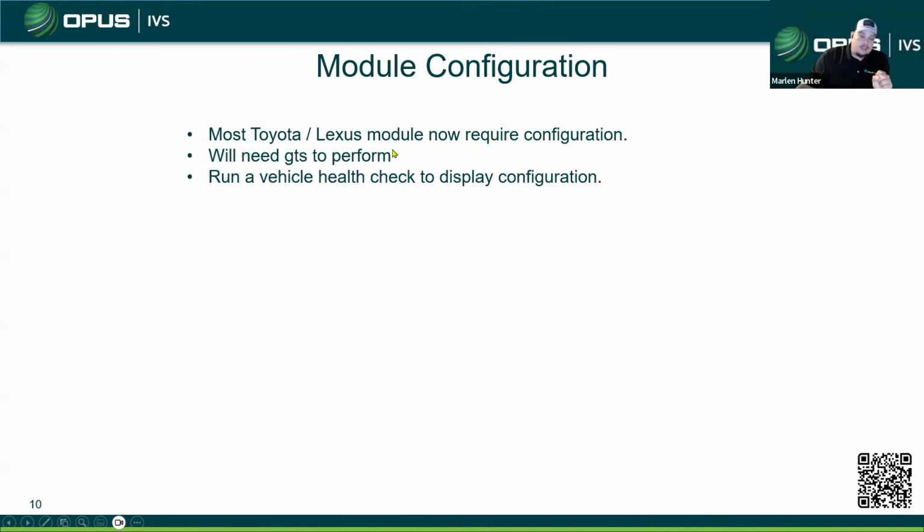Module configuration. There's actually a good service bulletin. I should have put it on here. Depending on the vehicle you have, that will show you a complete list of all the Toyota Lexus vehicles that require a module configuration. So what I would compare configuration to is, I would say, similar to Ford as-built data.